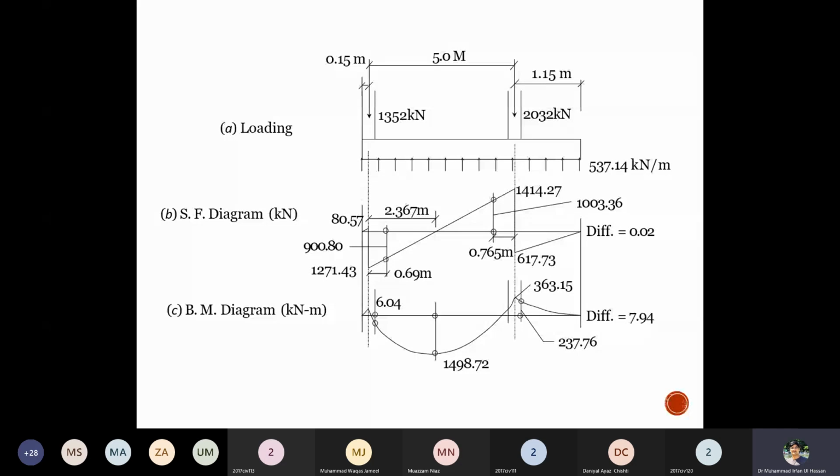The point is that at this level you have already studied the shear force and bending moment diagrams, and you need to determine all the locations: the point of zero shear, the point of maximum negative moment, the point of maximum positive moment, the shear and the moment at the face of the column, and at the center of the column, the values and the magnitudes, because we have to pick the critical values from this diagram. If you are just computing a few values at the known points, you will not get the critical ones.